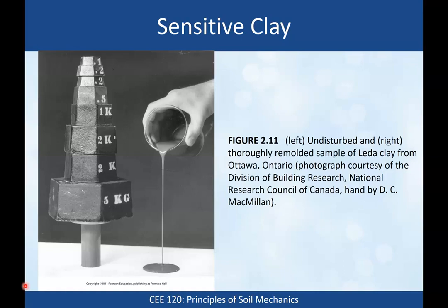It turns out water also has a slight positive charge, so you get water adhering to these minerals. And the water is not very strongly positive, so the clay minerals stay far apart from each other, and the positive end of the clay mineral doesn't click onto the negative surface of the clay mineral because the water is keeping them far apart.